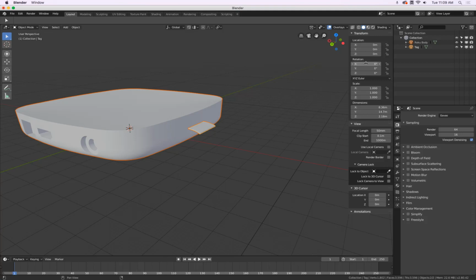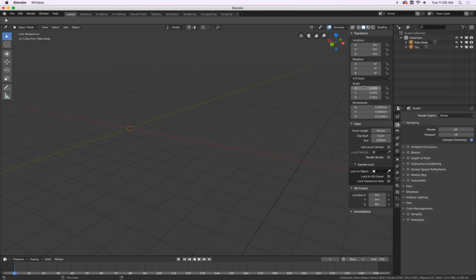Very good. The scale is too big. So currently the object is 2 meters tall. That's quite big. I could walk into this. We have to adjust the scale. Here again, I can adjust object by object. Or I simply click the label, click the base, holding Shift obviously, hold the Alt key, click and drag, .001, enter, and